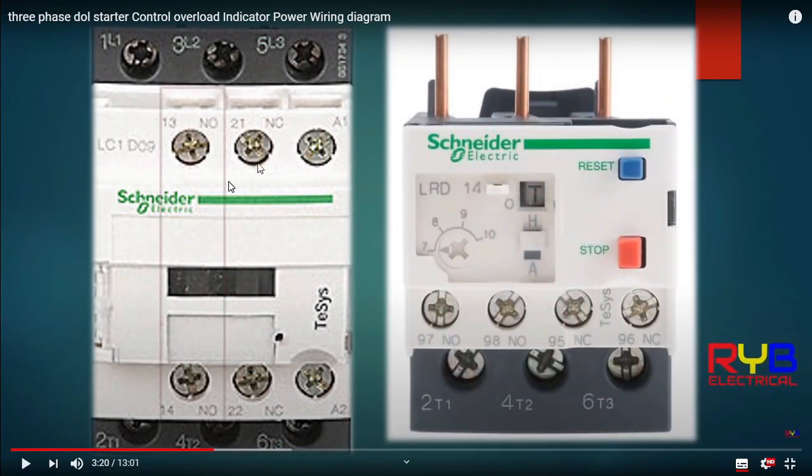Okay, this one is the contactor, and this one is the overload relay. We have normally open, normally closed, and auxiliary contact. This one is the stop and the reset button. So when this trips, there will be a problem on the motor side or the load side.